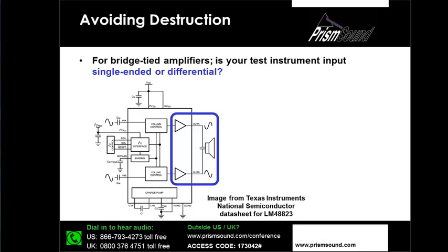So in other words, if you were to take perhaps an oscilloscope probe that was mains grounded on the ground input and connect that to this particular amplifier, you would be in trouble basically. You would be shorting out one of the output terminals. If the amplifier is smart enough, it may just shut down or mute. If it's not, then you may see that rather unfortunate pile of smoking semiconductors that we were hoping to avoid.